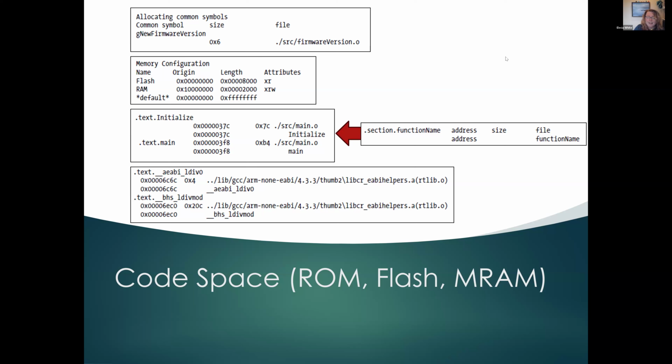The files are hideously ugly, but sometimes they provide the only way to truly understand how the code is functioning on the hardware. There are other files you may need to dig into, files you've never seen before. Linker files describe how you want the memory map to be. Assembly files cover how the system starts up before you ever get to main. And list files describe what your code looks like to the processor. But I'm close to out of time, and that is why I wrote a book, to explain things like that